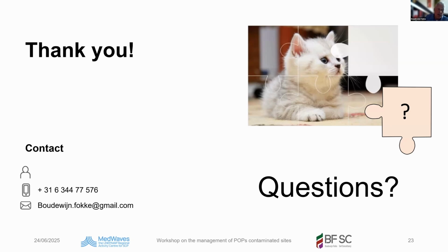It's now already 10 or 15 years ago. The city of Amsterdam found it an unacceptable situation, and they asked two companies to remediate this site. And it was impossible. After many studies, it was found impossible to take away this waste. It would have cost too much. So at the end of the day, it was decided to contain the risk, and containment is the last resort to manage a contaminated site when you do not have enough resources. And this was the case in our country. So the 100-hectare dump site with dioxins, with a lot of other chemicals in drums, pure products, was contained.